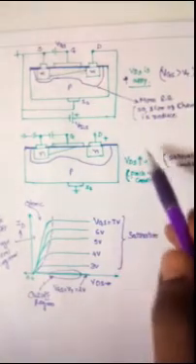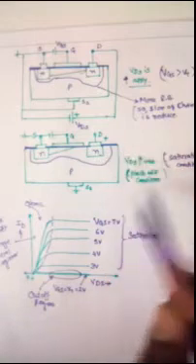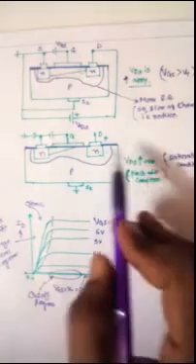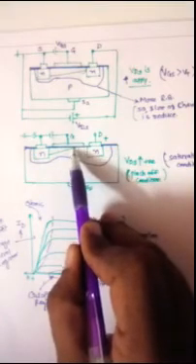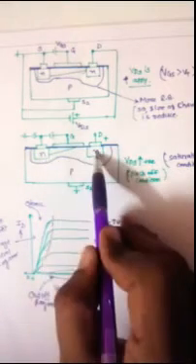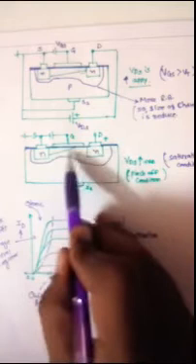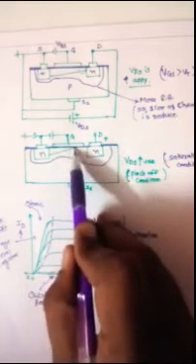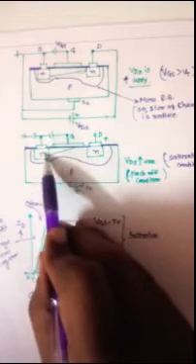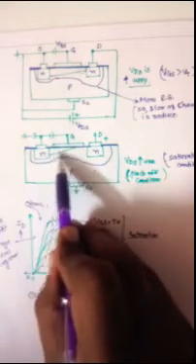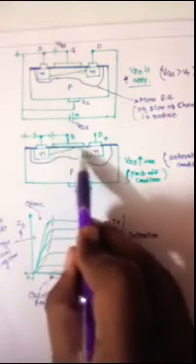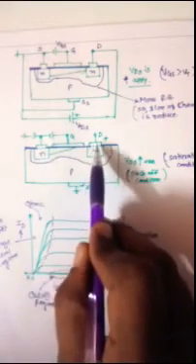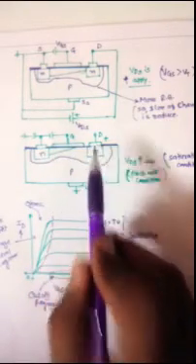Now we further increase the voltage VDS. What happens? A condition arises where no current can flow between the source and drain, because this is the pinch off condition. Then the electrons are going through the channel, and the flow of electrons goes this way in a saturated condition. So the current will be constant.